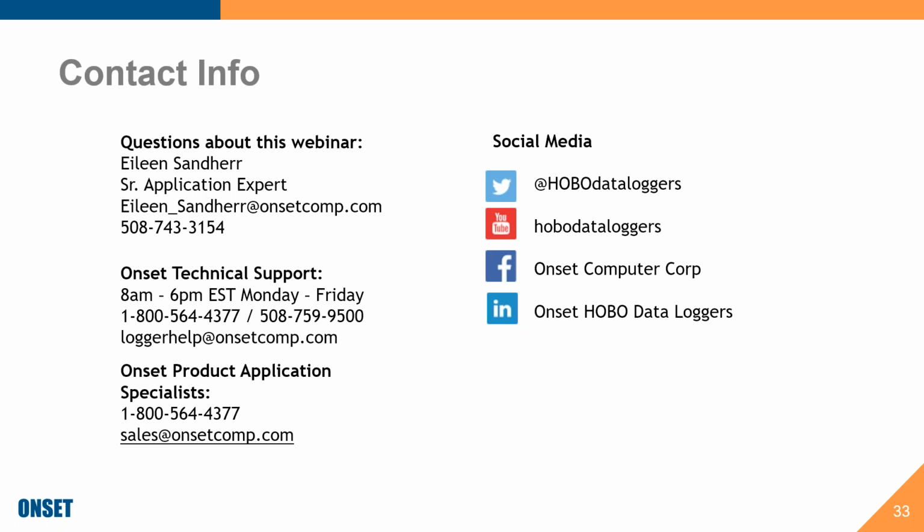Awesome, thanks, Eileen. Can you talk a little bit about the difference between our water level loggers, which are non-vented, versus, I guess, vented loggers in general? And I'll clarify that by saying we don't sell vented water level loggers, so we're not the experts in that area, but we certainly can tell you more about our non-vented version. Yeah, the non-vented is really very convenient because you don't have to worry about vent tubes kinking and clogging and being cut and damaged. So we do not use the vented loggers typically.